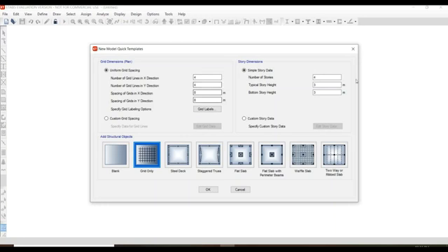Now use the X direction grid lines. Their default values are there in the system itself. So if you want to change the number of lines or the spacing of the grid system, you can change it. Let us make this 5 lines in the X direction and 4 lines in the Y direction, with a spacing of 4 meters and 4 meters. If you want to customize the grid spacing, you can do it by this option.